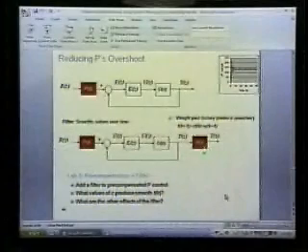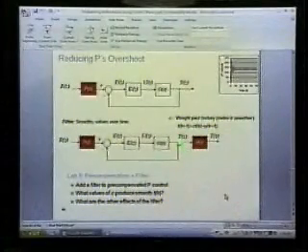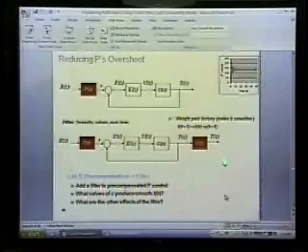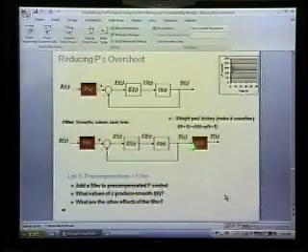So we've got the precompensator. One way of dealing with the overshoot is we can smooth things a little bit. So instead of taking the output as it stands, we've got this system over here. We're not going to muck with the system. We're going to essentially put in this control add-in, H of Z. And what this does is filter things so that what we actually see on the output is something that's smoother.